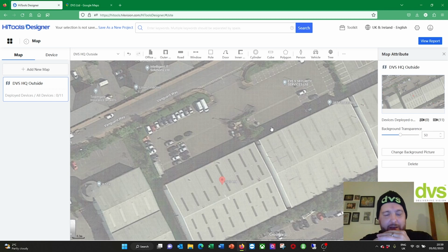So it definitely is worth taking the time. Use Google Maps. If it's an outside area and you want to do perimeter protection and it's on Google Map, get the measurement, and then you can set the scale on your drawing here. If you don't know the scale of Google Map, like the building doesn't exist, there will be other ways that you can do that, or use something that's close in size to that and just reference that.